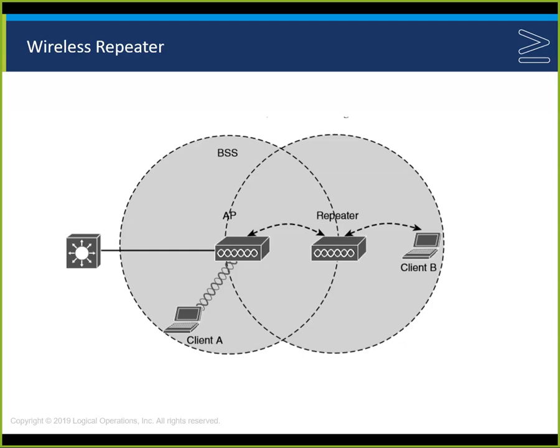The more sophisticated protocols that we have now allow multiple connections, but typically we're going to have a single connection. So what this says, we need the two frequencies here in order to communicate from one to the other. We're going to need, let's say here, the pink frequency to go to the repeater, and maybe here we'll have the black frequency to go to the device, so that they're not interfering with each other, because they obviously are within range that they could overwrite one to the other. If we had a single frequency to do this, then we would go to here to this one, and then we would go on back.